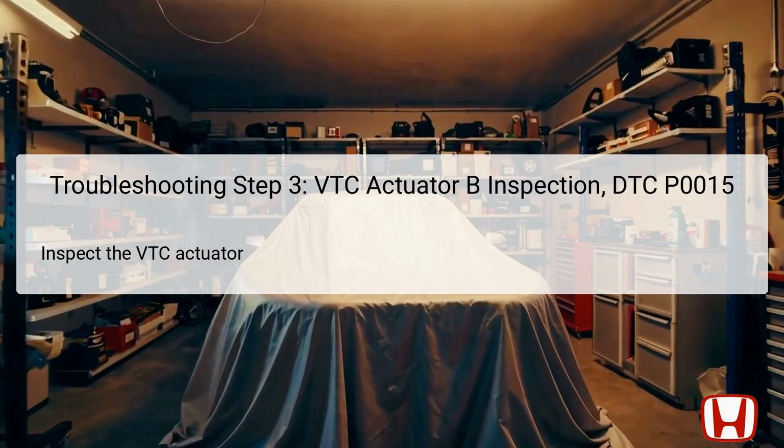Additionally, listen for any unusual sounds that might indicate internal failure. You should also assess the electrical connections to ensure they are secure and corrosion-free. Any defects found during this inspection may result in incorrect timing operations, directly leading to the DTC indication. Based on your findings, appropriate repairs or replacements can be carried out.